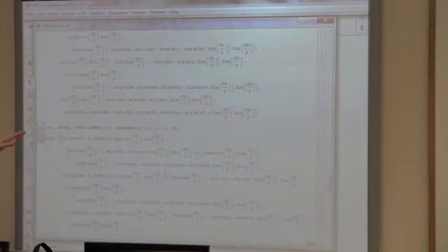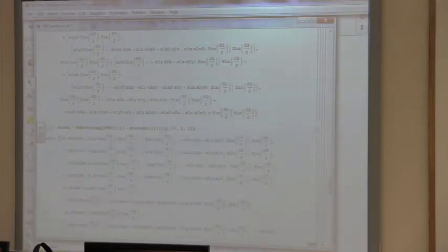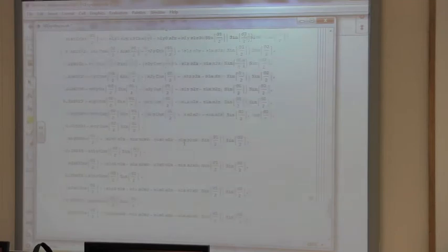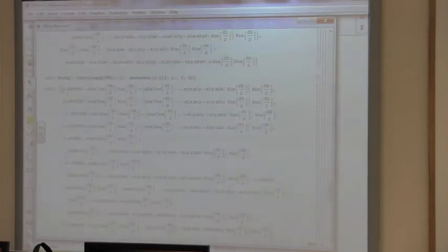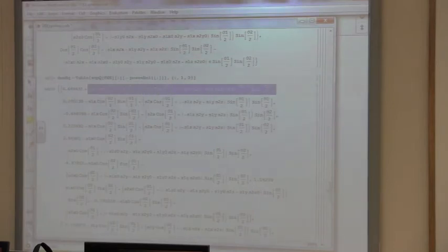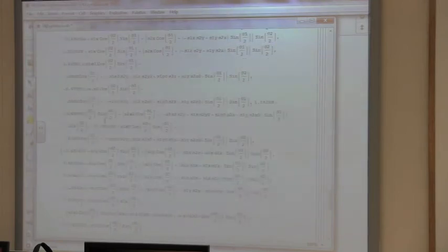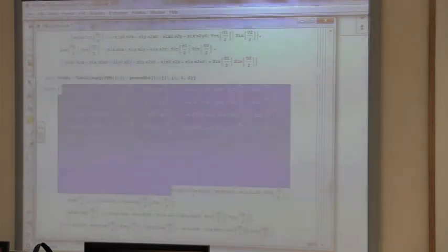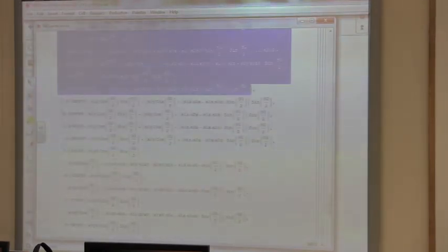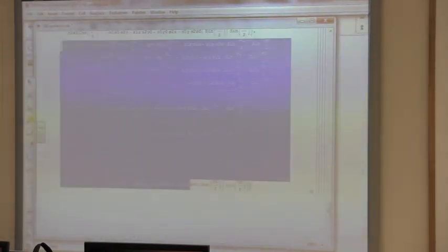This has the epsilons and all, and in order to solve for these equations, let's get rid of the epsilons. So let's do a sep q for each of them. Sep q, which separates the components and gets rid of the epsilon. Okay. All right. So now we have our system of equations. This is our system of equations. This is the desired position equated to the component of the dual of the forward kinematics and so on. And this is the first set. So this is the set for the first position, and this one is the set for the second position.